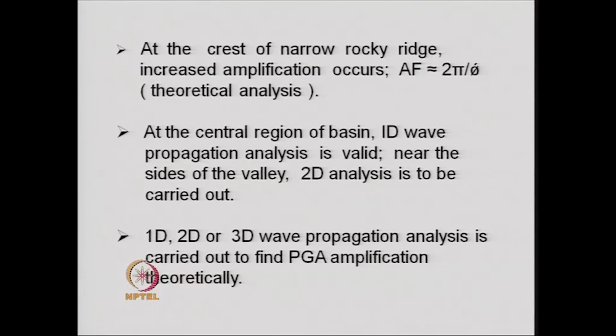At the crest of a narrow rock ridge, increased amplification was observed. The amplification is of the order of 2 pi by phi, where phi is the included angle of the ridge.